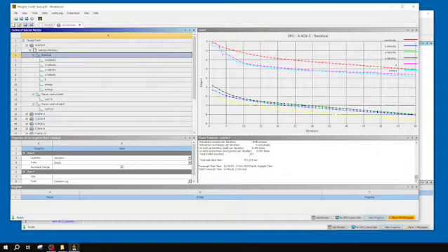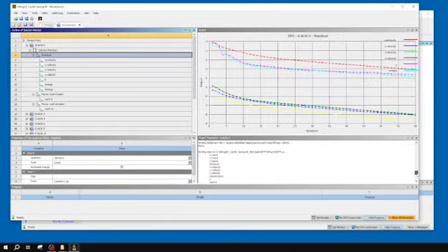So this first is another zero case, and I actually didn't abort this one. The solution ended up converging. How I believe Fluent has defined convergence is it looks at these residuals, and once everything is less than 10^-3 on this plot, it'll consider the solution converged. Remember, this is a log scale, so once continuity popped below that -3 as our last point, it decided the solution was converged and ended it on its own.